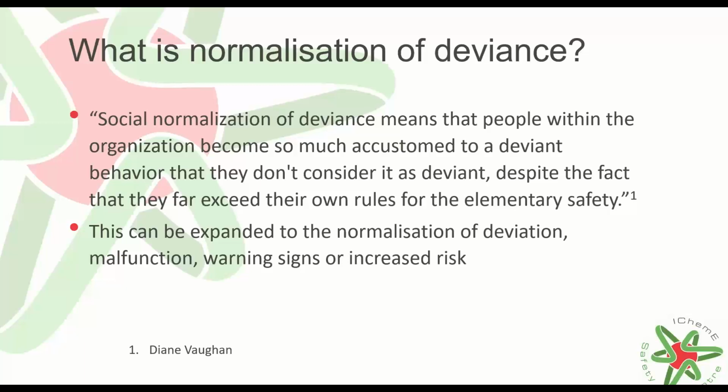If we've got our plant operating within its normal operating parameters, but it moves from being in the mid-range to being towards the higher end of its parameter, that might be a deviance that we fail to notice because it happens slowly over time. And all of a sudden, we're at the point where we have the plant operating in a different way. It might still be operating within its normal operating envelope, though. So that's an interesting aspect too.